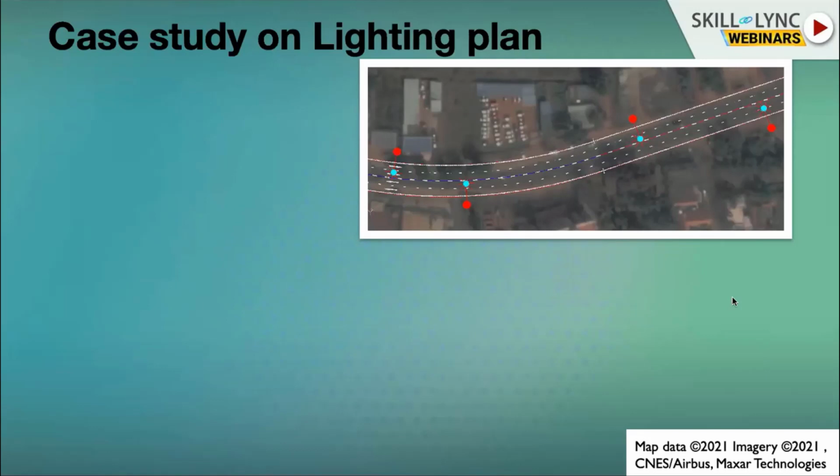So here we can place it in a staggered manner. Staggered placement of the single post street lighting can be provided here, since the area is smaller for the minor road, and the output of the single post has sufficient spread and luminosity that they can be placed in a staggered pattern at higher intervals rather than at lower intervals, as it's been placed at the junctions and on busy wider roads.